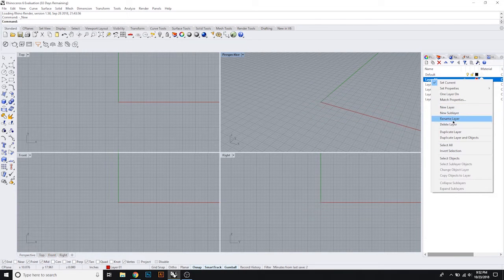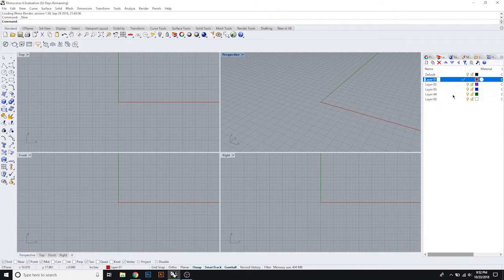So for this one, why don't we rename our layer object. And the second layer we're going to name dowels. And the third layer we're going to name cut sheet. These refer to the object we're going to make, the structure of it, and the laser cut files that we're going to put on. So we can add some sublayers.